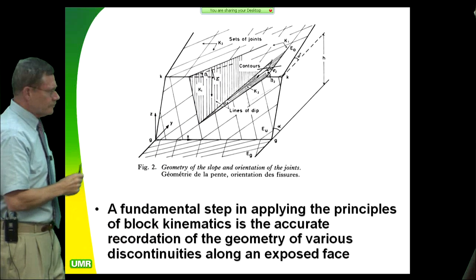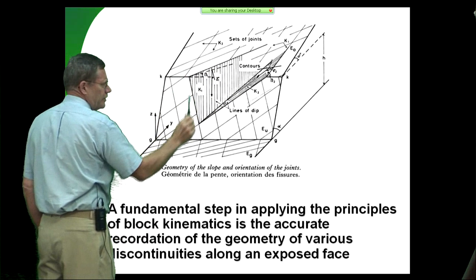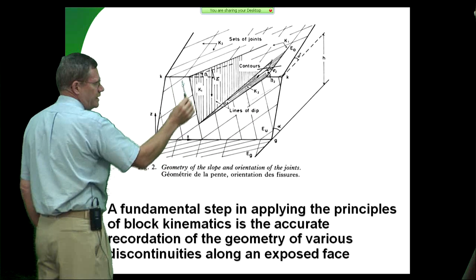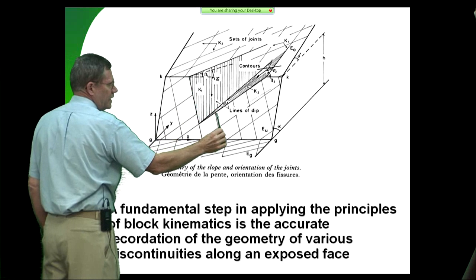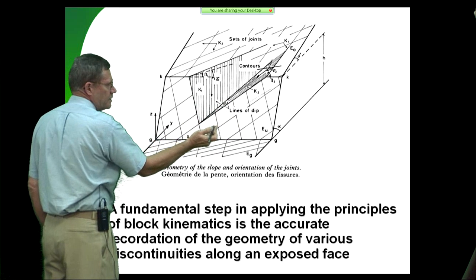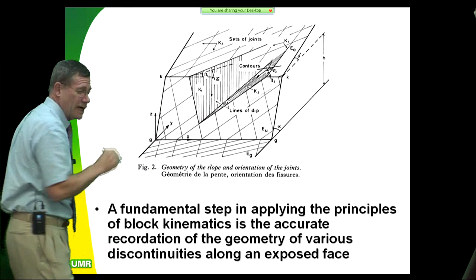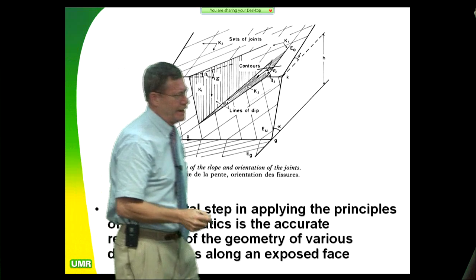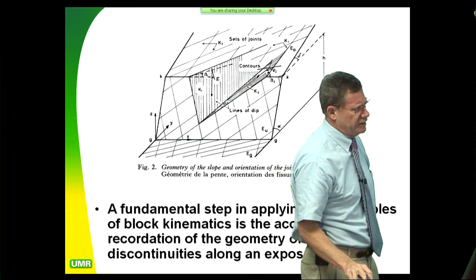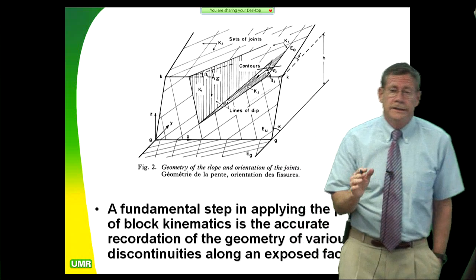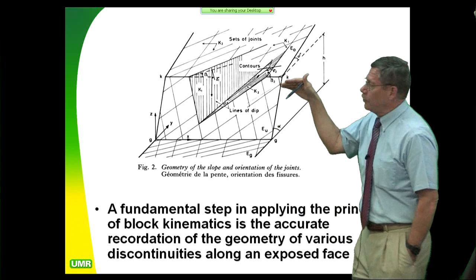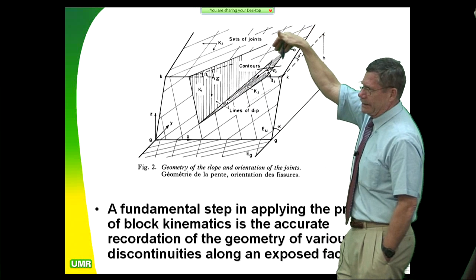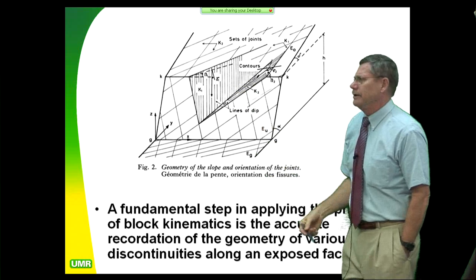And so in this kind of stuff, when you take a picture of it with your LiDAR, you don't always get the true geometry of these joints. You have to have some sort of exposed face you can put 3 points on to get that, or you have to go out there and actually physically measure it ahead of time if you want to do an assessment of it. But these are very, very susceptible to pore water pressures. So if you get pore water trapped in here along this lower one, so the water comes running down here, gets trapped in there, that's when you get the trouble.